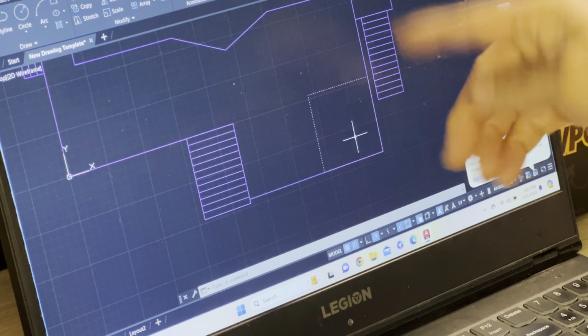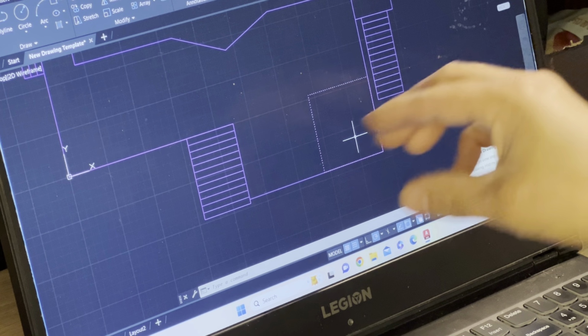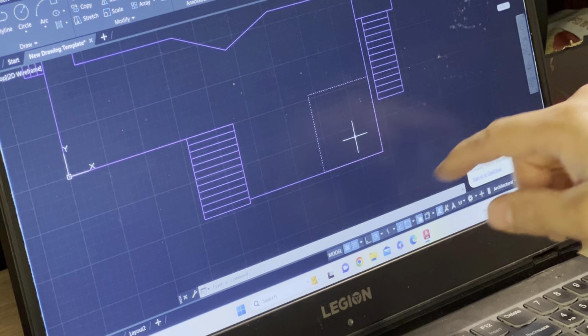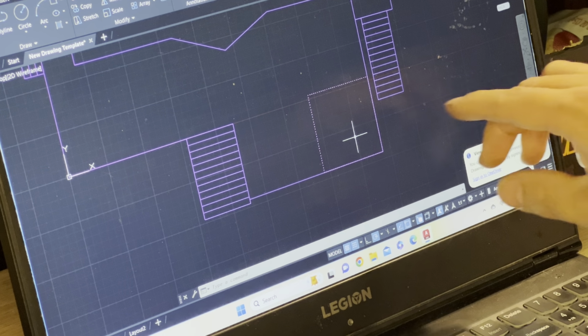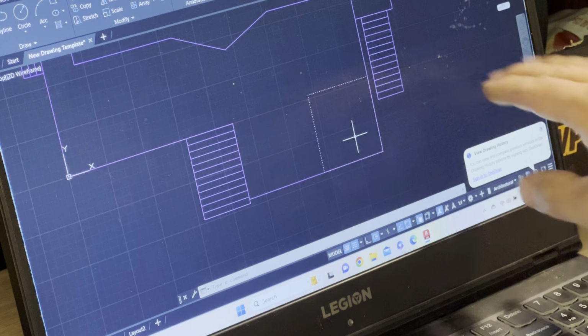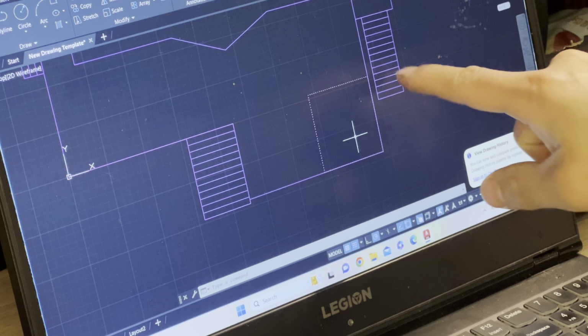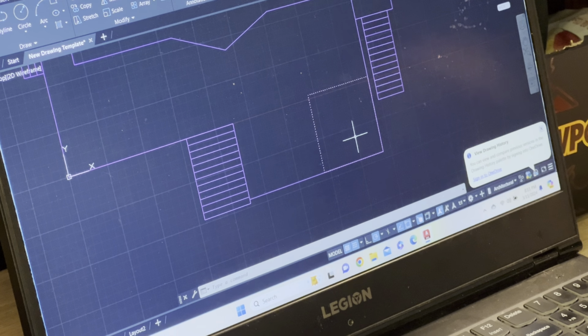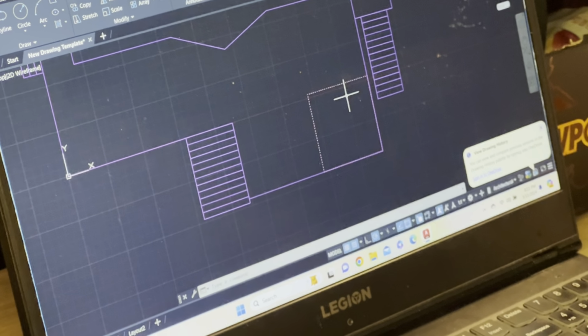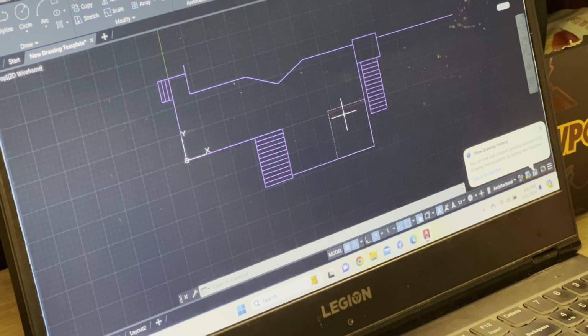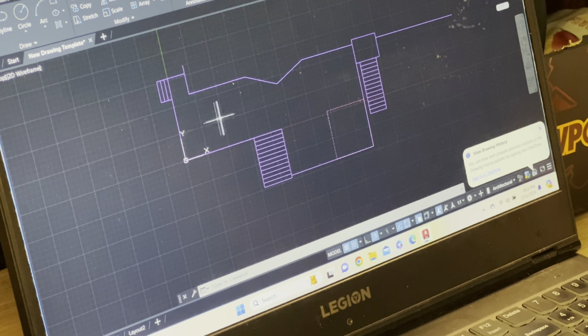But if we dig down and rebuild it around, we can give him a 10 by 10 storage under the deck, accessing in and out on level ground, right where the bottom of these new stairs are going to land, right? So that's part of the job that we're hired to do: we're going to remove this corner of the dirt, and then we have to do some regrading here after we dig our footings.